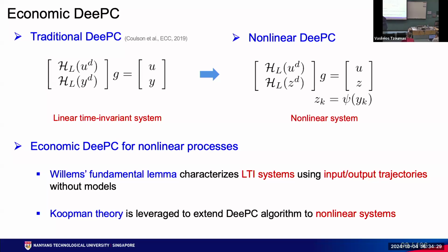The CO2 concentration in the flue gas of a ship, depending on the operating condition, may fluctuate from 2% to 8%, so the state value basically varies from 1 to 4 or from 1 to 5. In terms of flow rates, it could be a multiplier of 10. The fluctuations are something we are not able to predict, but we must deal with. So I would say stochasticity and uncertainty.